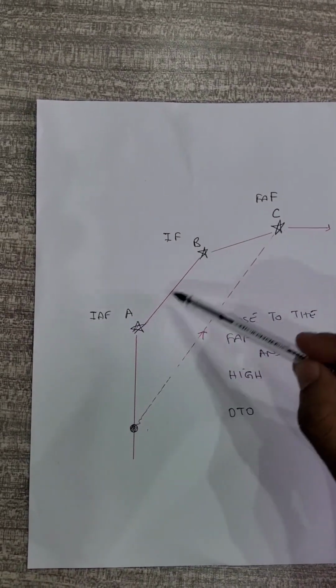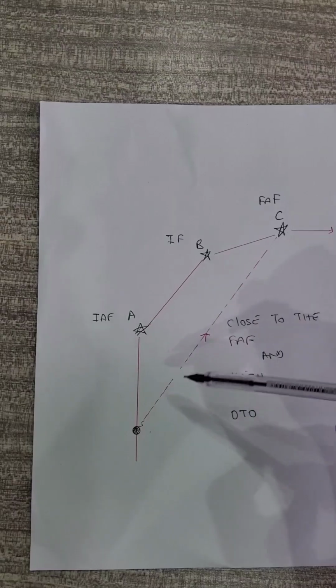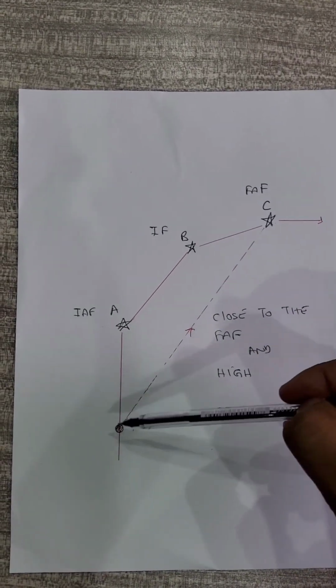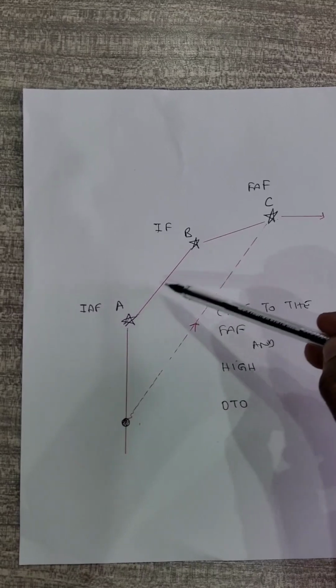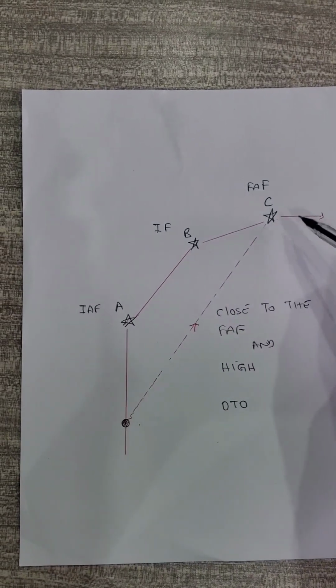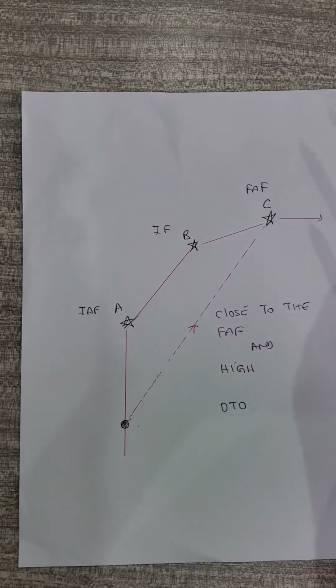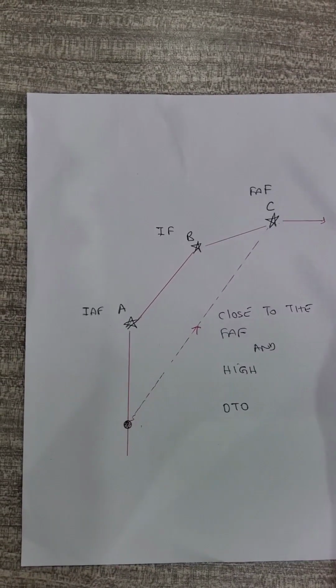This is a CDFA profile, if you know what that means. It's called continuous descent final approach profile. It's already calculated here initially when you program the FMS, but now you've disturbed it by just doing DTO there without telling it what to do.